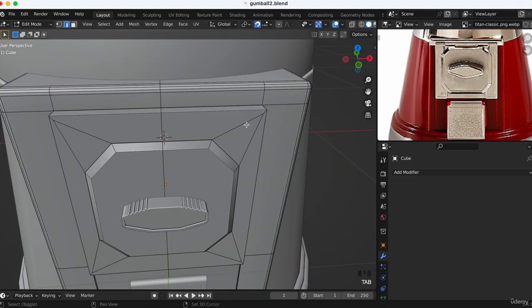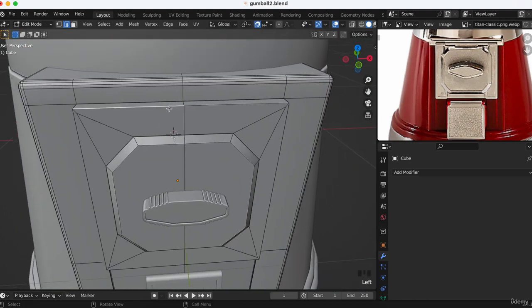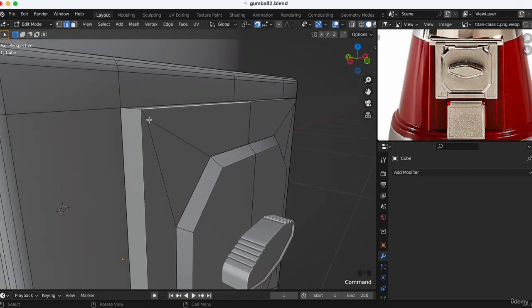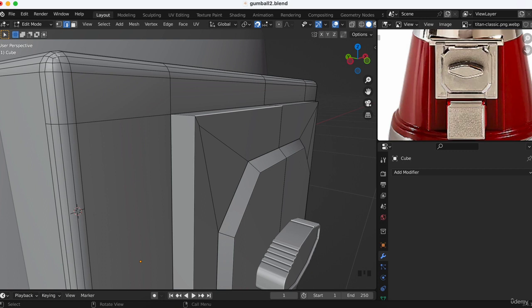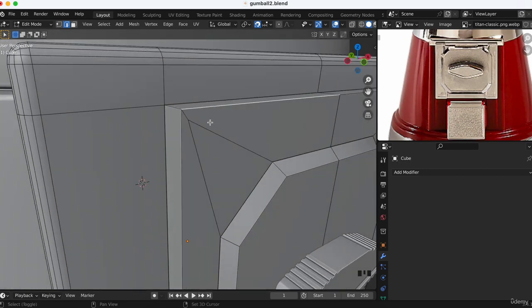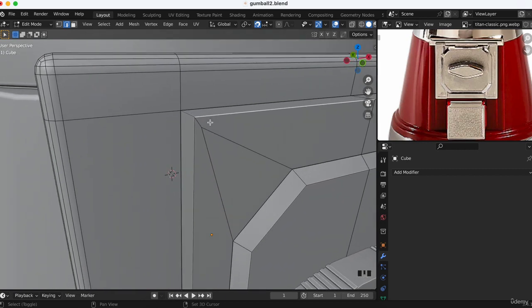this part here, and we need to make a little bevel because we don't want the lines. You see, when we did the bevel here, it created all of these segments, and we don't, when we are doing this here, we don't want to touch this part, or there's gonna be shading problems.